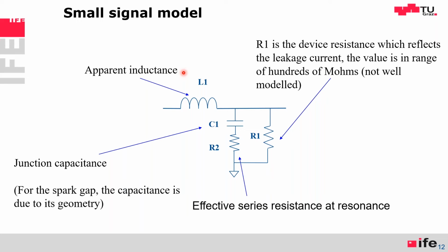Now there's a junction capacitance here. I told you that's from maybe 0.1 to, of course, high values, but for high-speed design, usually just 0.1, 0.2, 0.3 picofarad.